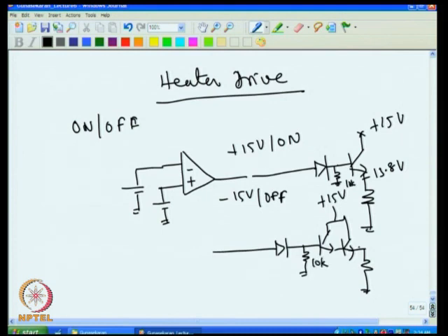The Darlington pair can be used for high power current, because the current in the base cannot be more than 10 milliampere, as most op amps are rated for 10 milliampere output current. So, in this case, if the HFE of this is say 100, then with 10 milliampere, 1 ampere current can go through this. The transistor should withstand that much power, because when it is on, about 1 volt is there and about 1 watt heat dissipation will be there when 1 ampere current is flowing.